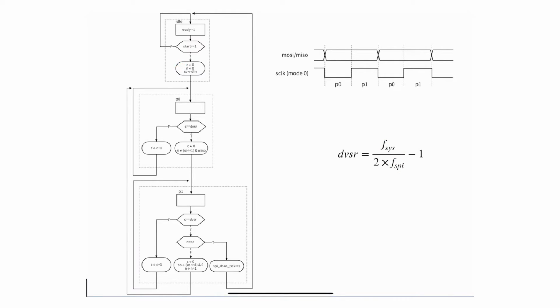So the C register, in any of the modes, in any of the states, you'll see at the very end of it, before you leave, you're putting a 0 in it. Like if you're leaving to the next state, not repeating, because if you're repeating, that means you're just basically staying inside here. Okay, so its purpose is just to make sure that it tracks the SPI clock. That's what the C is.